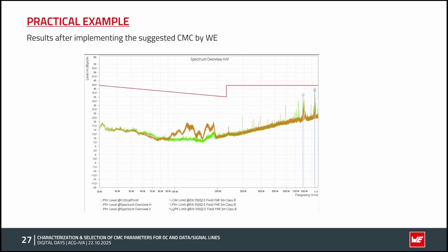Not a problem. The most important thing is that it's filtering, you are passing the standard, and also your signal is not being affected. So if this is working, perfect. You can go and buy the common mode choke selected.